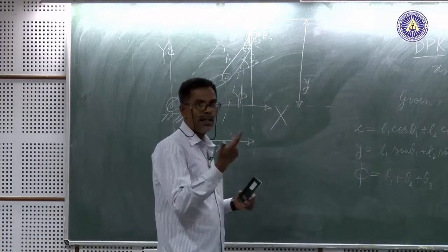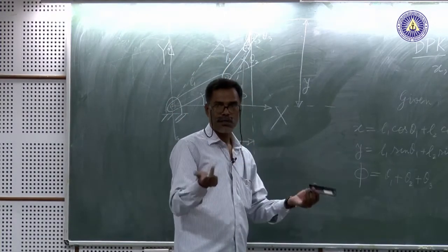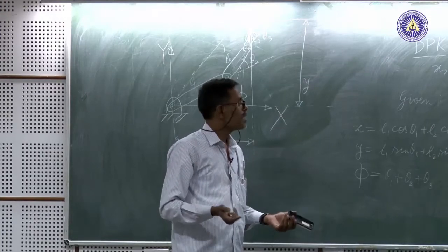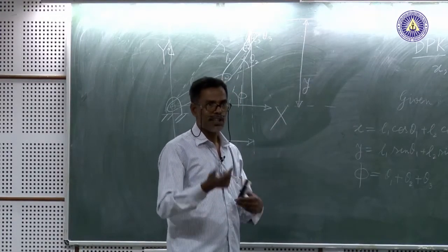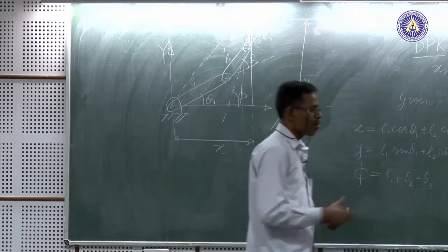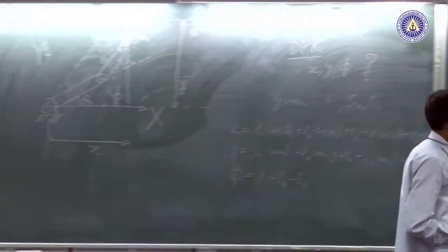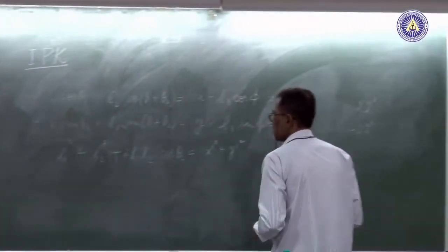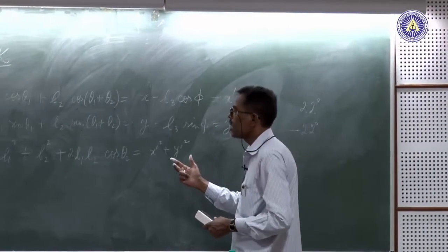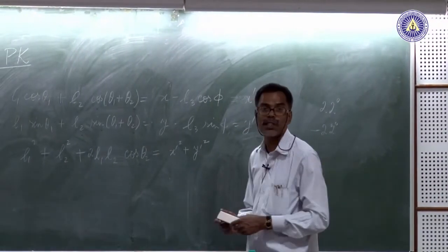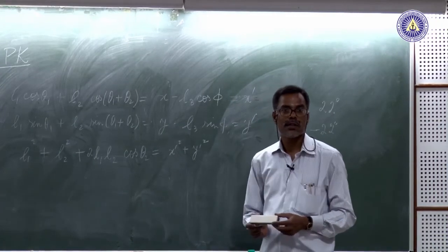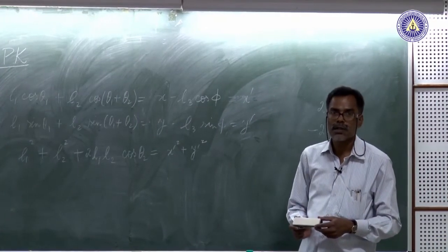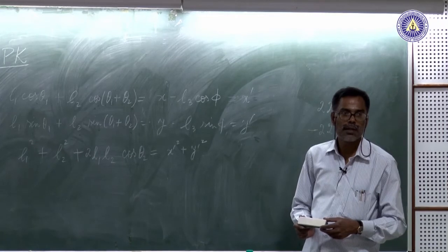So, these are the branches of the inverse position kinematic solution. Typically, they are called elbow down and elbow up. So, like this and like this. So, you get theta 2 two values from here, and once you get theta 2, how to get theta 1? Pardon?